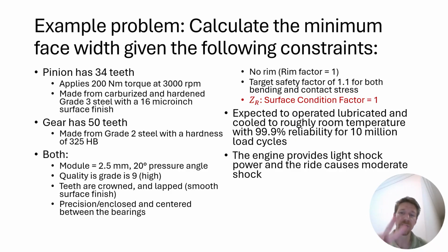What's our approach going to be? We're going to calculate not just one, we're going to calculate 2 face widths, one based on the bending criteria and one based on the contact criteria. But before we get there, we have to calculate the load and the modified load.